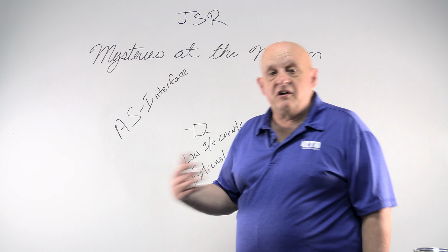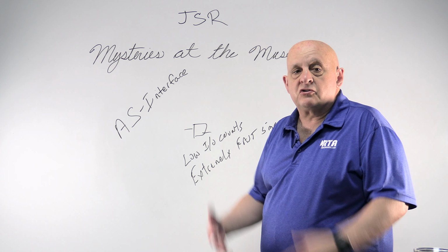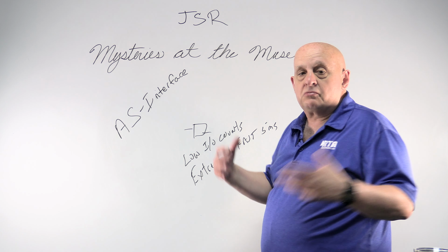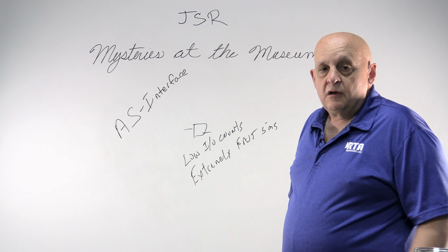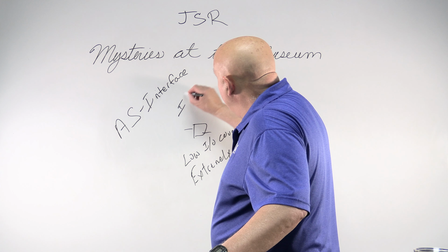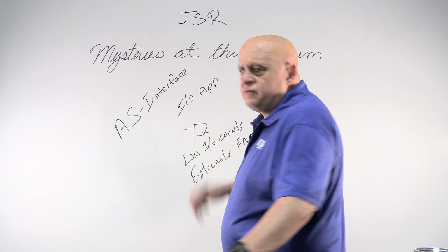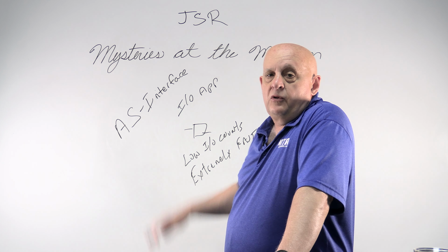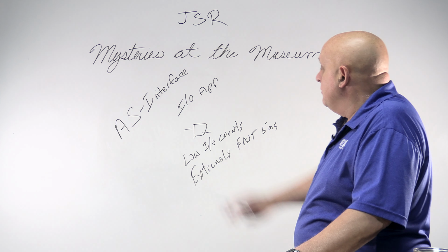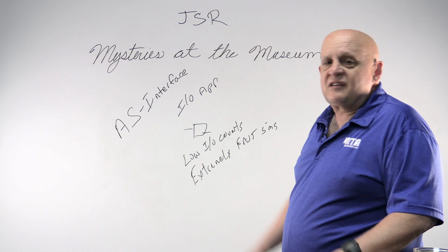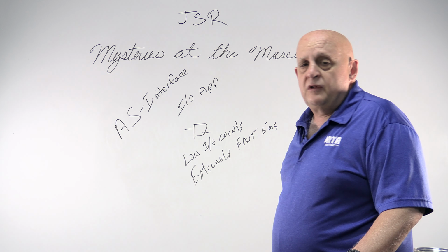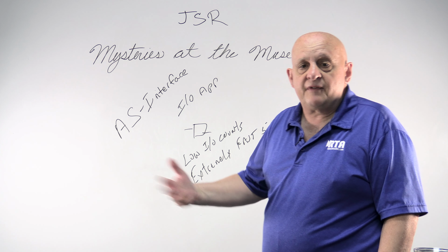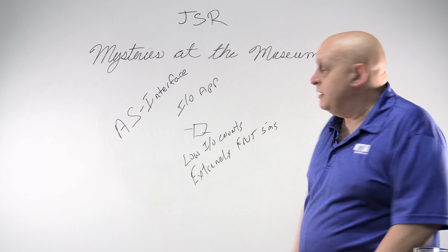So this was good enough for lots of industrial automation applications. Where you used to do hardware direct connects to a PLC, you could now use AS-Interface and just replace that hardware. So this was used for lots of different kinds of I/O applications, mostly just for sensors. If you think about this, this is really the forerunner to IO-Link. IO-Link is a lot more integrated and easier to install. Though AS-Interface is easy to install, it has kind of fallen out of favor. IO-Link has really surpassed this. And you're still going to find a lot of AS-Interface if you walk around different kinds of plants.